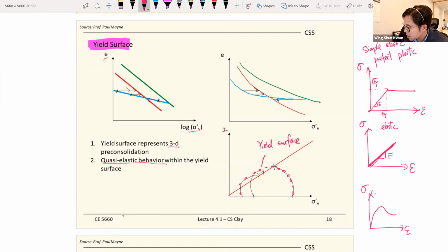So this is kind of the yielding surface that we talk about, just a line in 2D, but a plane in 3 dimensions. So you need about 3 parameters, versus 1 parameter for simple elastic. But for soils, you need many parameters to be able to do it.